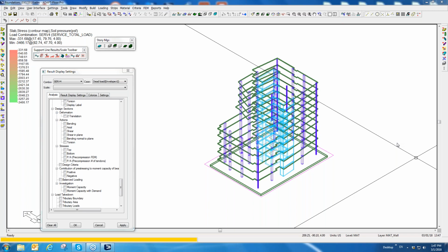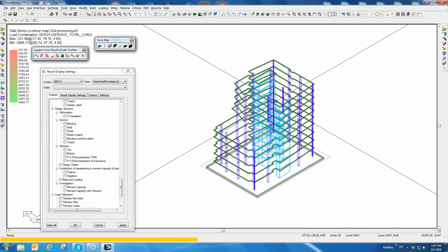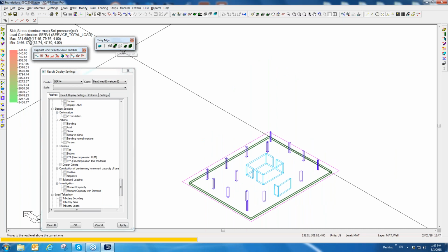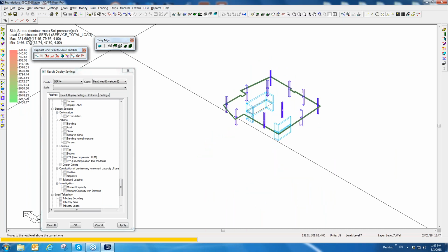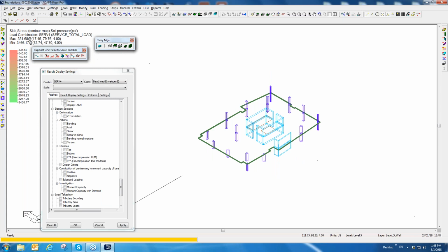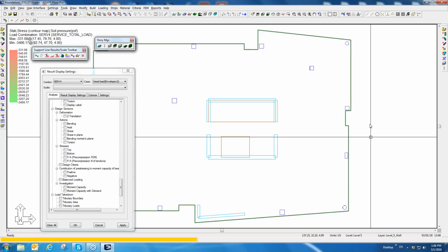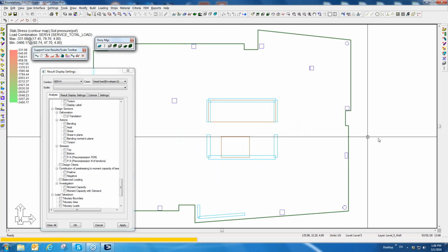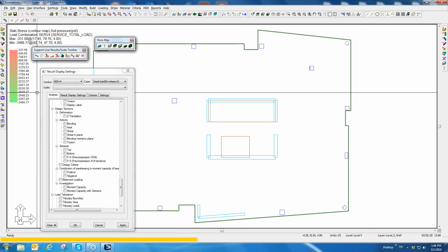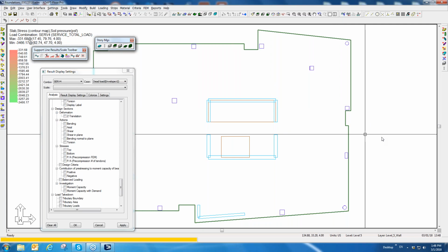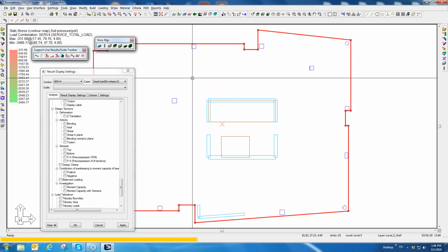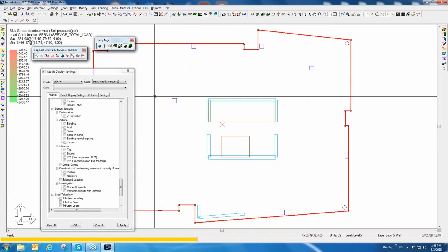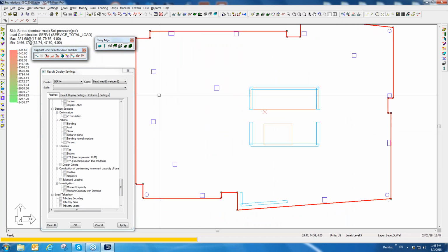There's not. You can model trapezoidal area loads that might be a good thing to use. There's no explicit input, but let's say right here where the floor plan changes, along say this line, you have a step in the building, so you might get drifting on this roof right here.